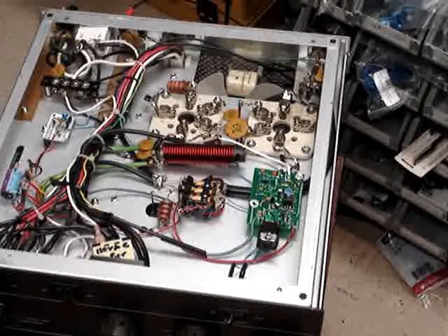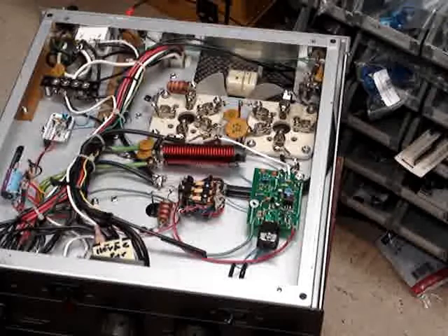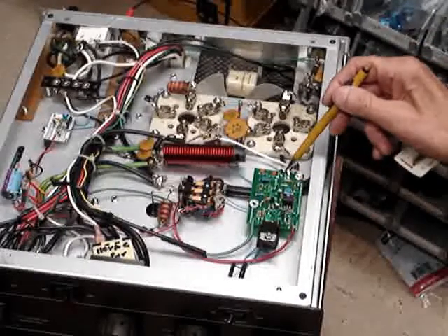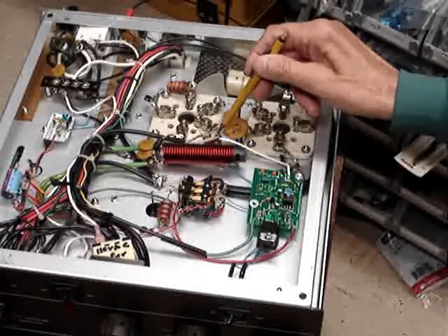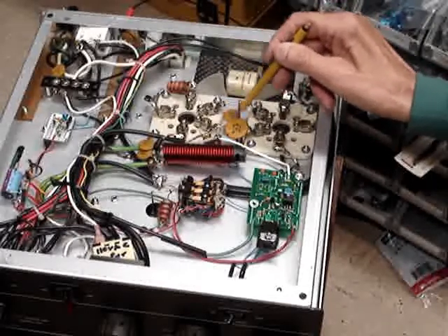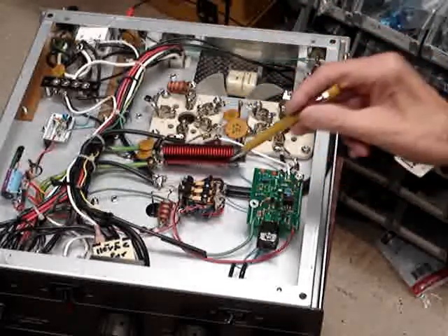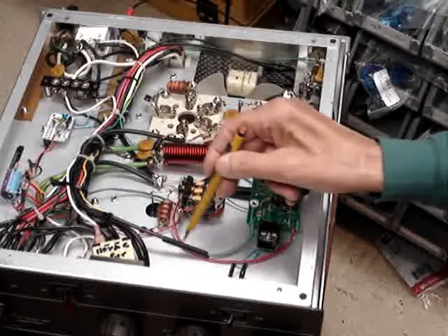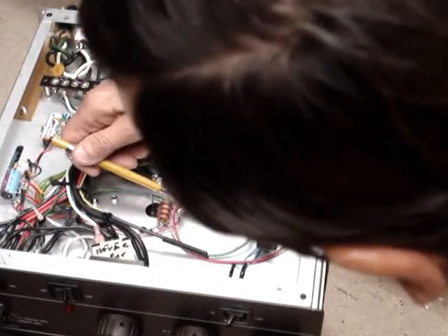Okay, now here's the electronic bias system circuit here in the HL2200 Heathkit amplifier. It's the equivalent of the SB220 Heathkit amplifier in the area we're talking about as far as electronic bias. Here's the circuit. The RF input and ground are right here. So here's the RF input going over to where that matching network comes into the tube. There's the two capacitors that are feeding the cathode or filament. And here, this black wire was originally right here where this red wire is on this relay, on the lower contact down there.